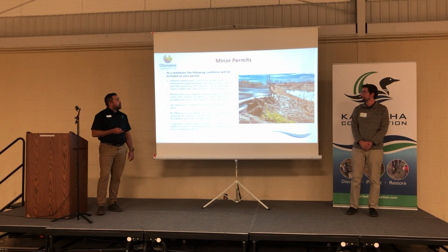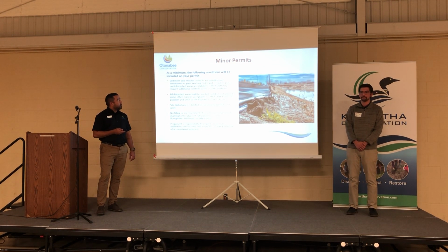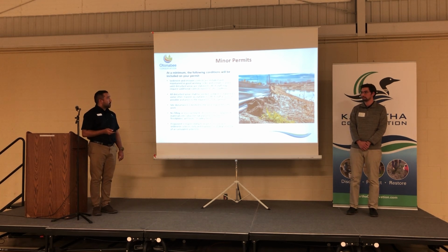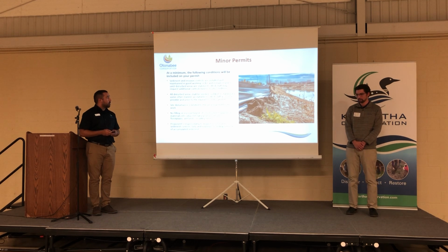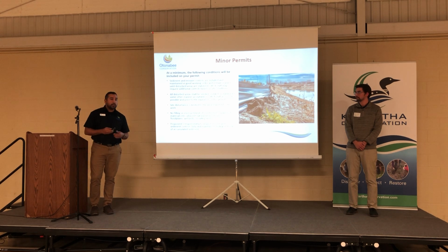For the conditions, a lot of them are fairly similar to what the conservation authority asked for. So just sediment and erosion controls installed and maintained in good working order, and that those ESCs remain in place until all site conditions are stabilized. And also keep in mind that once we do inspections on site, we may also ask that additional controls are installed depending on the site conditions.